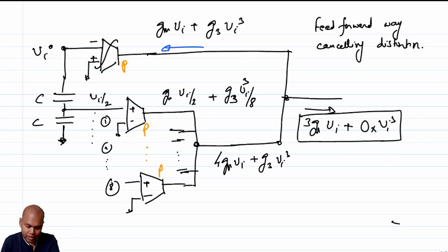There is another very popular, very cheeky way of mitigating distortion. This is particularly true for MOSFET circuits, right? Not necessarily for BJT or other kinds of circuits. But note that the previous way of mitigating distortion is true for any type of circuit. We did not assume any sign of GM or G3 or anything. It's a generic way of mitigating third harmonic, right?